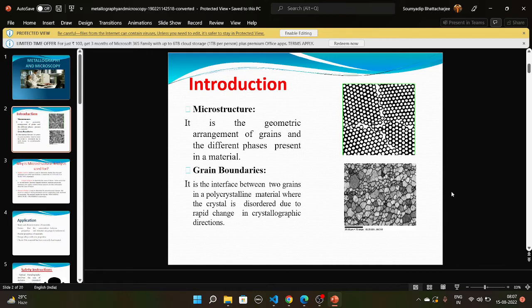Do you accept this? Because it is fixed at one end and the other portion is projected. This kind of cantilever, as we studied in strength of materials. And when you start cutting, start machining, some machining forces will be there. Cutting force is the maximum, highest force. Many forces are there: feed force, thrust force. But out of these, the cutting force is the maximum.